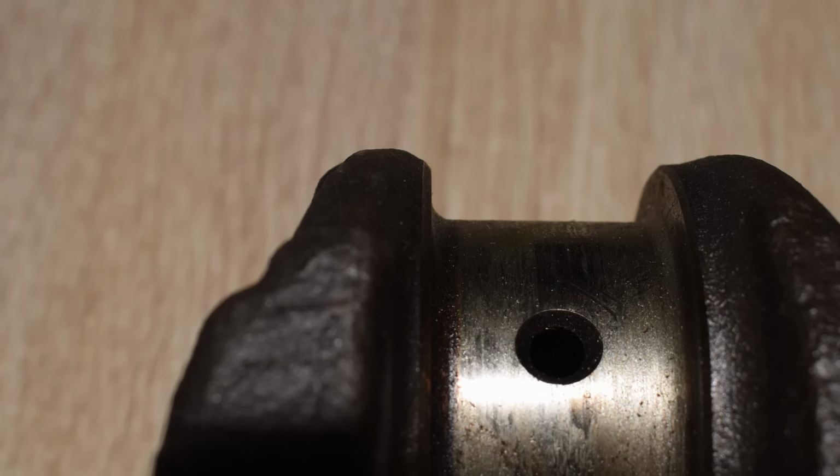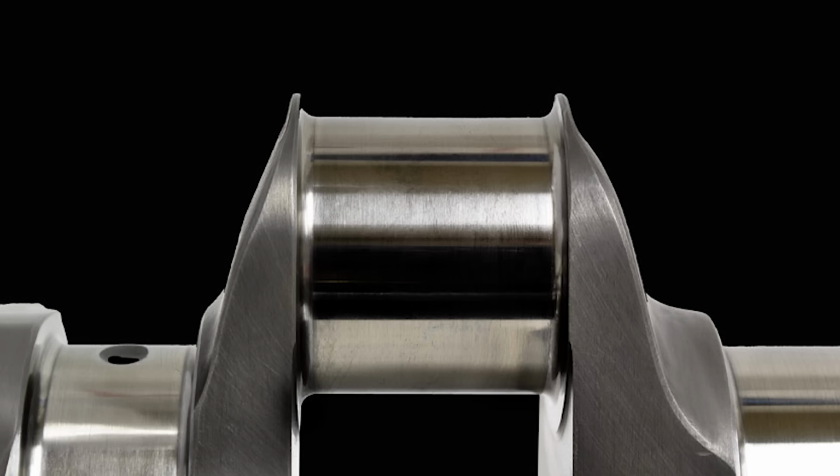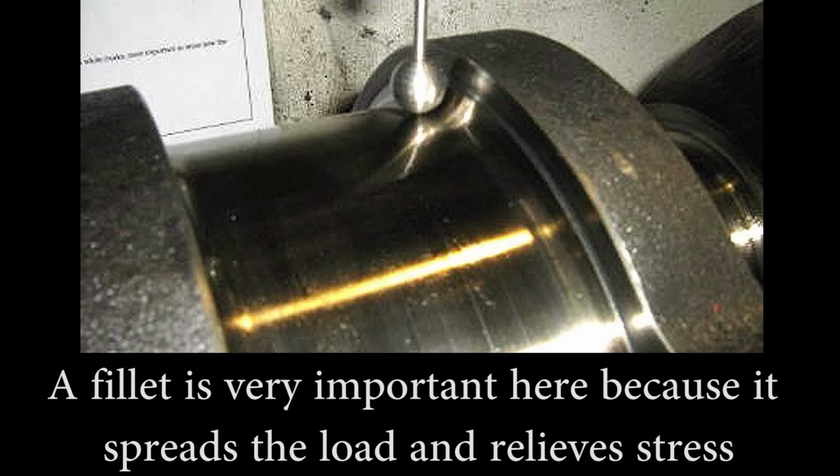Another very important design element of the crankshaft is the radius fillet. Engineers take great care when designing this because a proper radius fillet is key to a crankshaft not breaking apart. The radius fillet is key because it spreads the load and relieves the stress in what would otherwise be an extremely common stress fracture point in pretty much every crankshaft. Something that is machined at a perpendicular, at a sharp angle, is much more prone to a stress fracture when compared to something that has a fillet instead of a sharp angle.